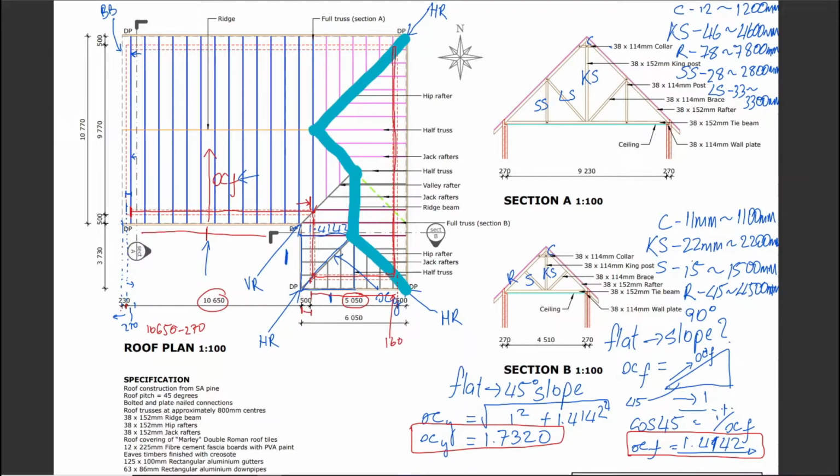So this face I've covered. This length you'll find on this side. So you'll take 3730, which appears to be the end of the roof covering, right? And since we know that it's 500, you've got to subtract another 500 to get to your outer face. Okay, and that's just your outer face. So now you've got to come in another 160, I would say.